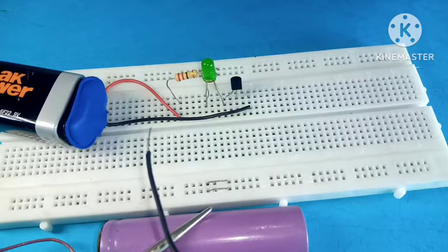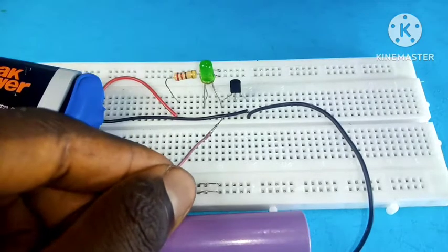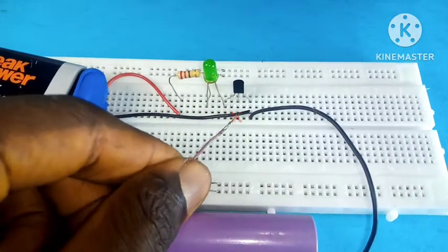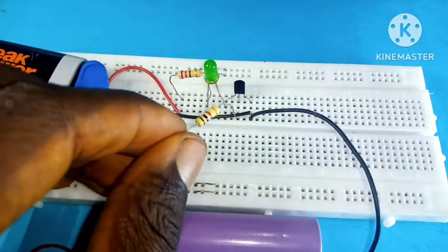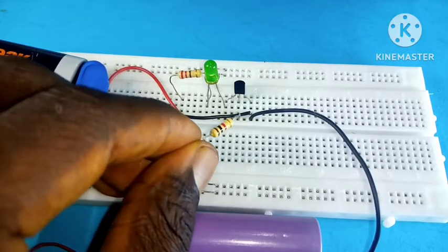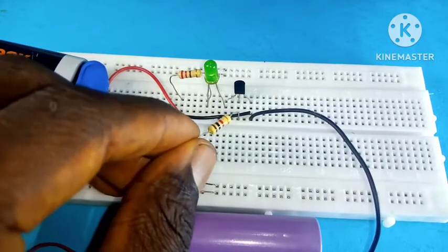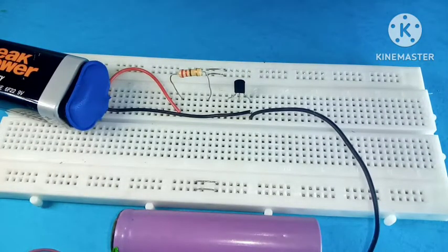Okay, let's see what happens when we use this 3.7 volt battery. So get its negative polarity connected to the emitter. Mind you, the emitter of any NPN transistor is always connected to ground. So let's see what happens when we take its positive to the base terminal. But wait, doing it this way will cause huge damage to the transistor, so we need a resistor to limit inrush current into the base from destroying our transistor. And we can see that our LED is turned on and it's brighter than before, but I'm going to use another LED. It seems this LED isn't bright enough for you to see.